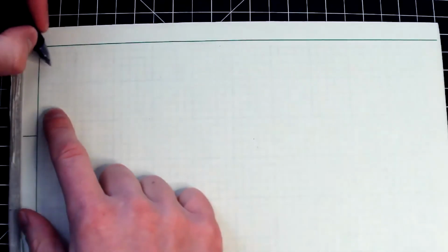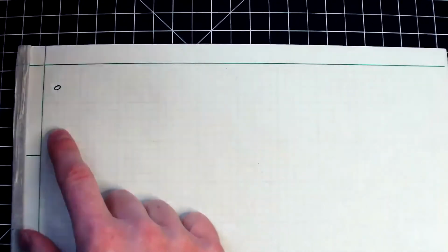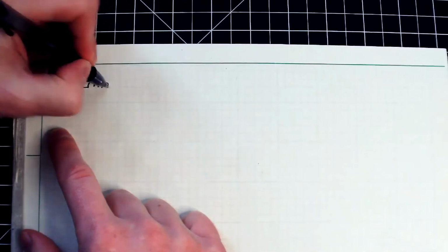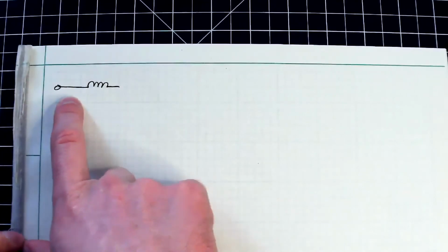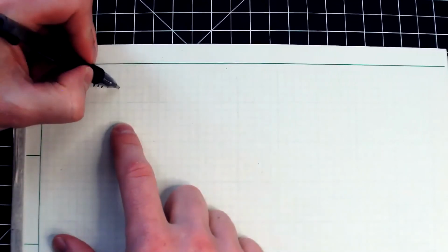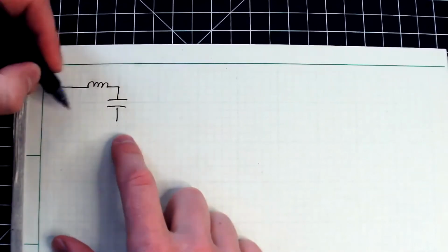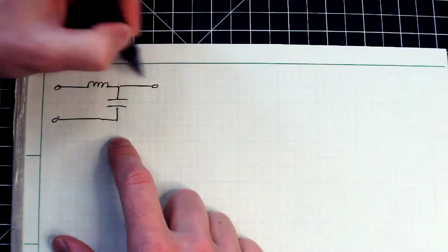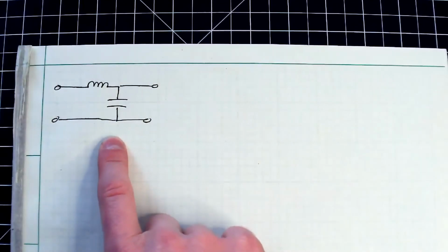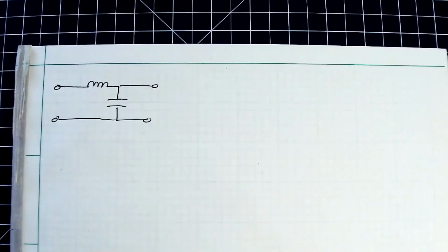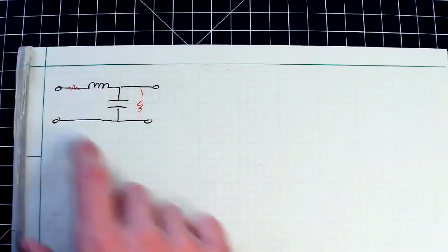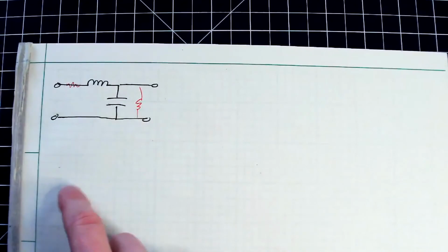The basic idea is, here is the ordinary transmission line model, where you have your signal line, there'll be some inductance, and I'm going to ignore the resistance here. And you had capacitance. That was your lumped element model. Remember, you could hypothetically have your conductance and a resistance there too.